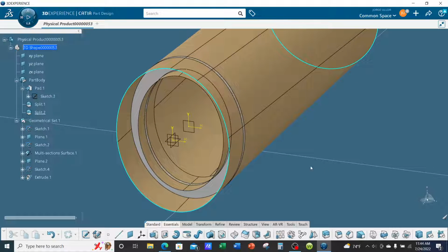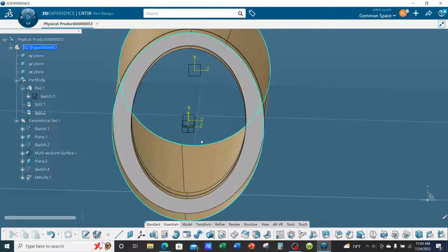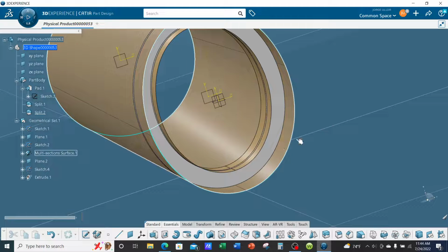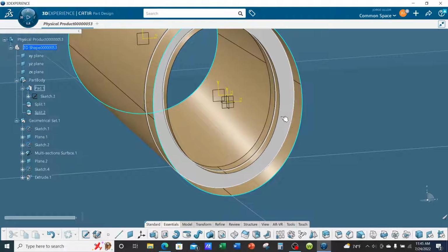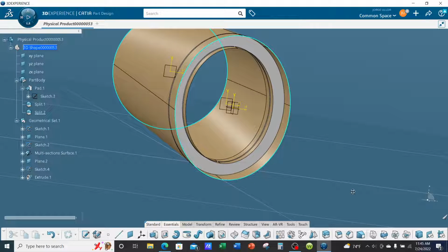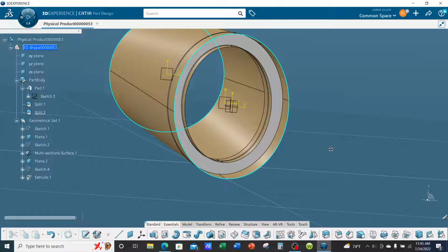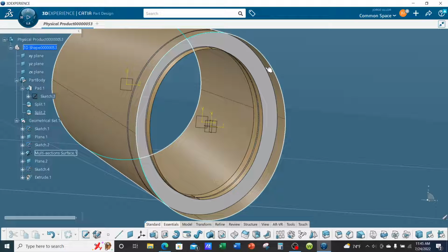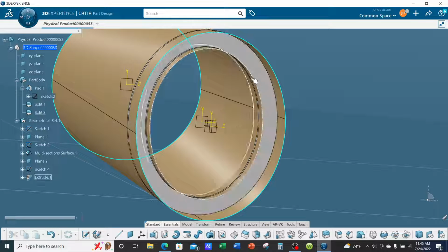All right, so let's say we're ready to machine off some of this area here that's not needed. We're trying to make it as lightweight as possible. So let's say our flange on the solid, we're going to keep a flange on the outside where it mates up with the skin, and then we'll also create a flange here on the inside.